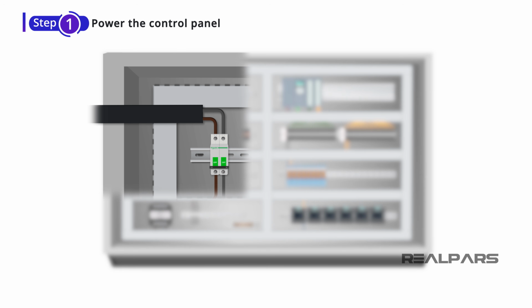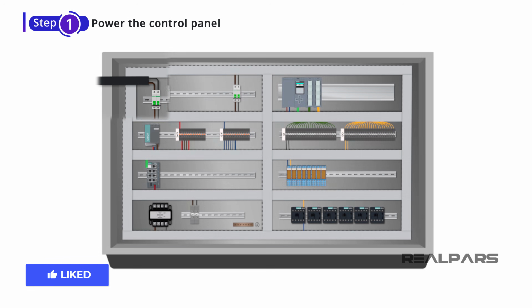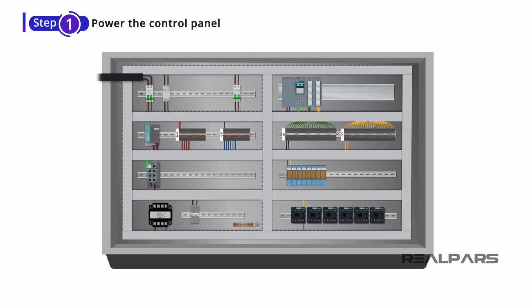The power that comes into the panel can be anywhere from 480 volts AC to as low as 120 volts AC, depending on where you are and the country you're based in. Once you have the power connected to the top side of the circuit breaker, you can switch it on for the power to flow to the control panel. Although this seems a very simple process so far, there are two important points that you need to consider when trying to power on your control panel.